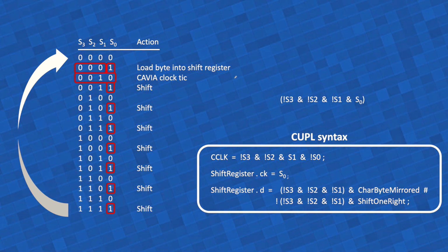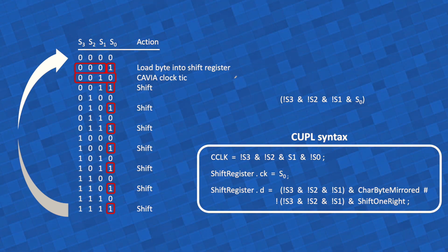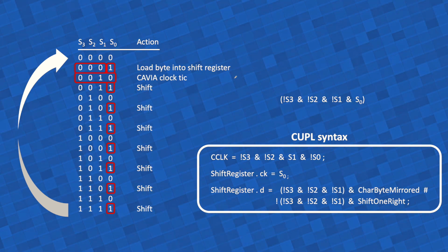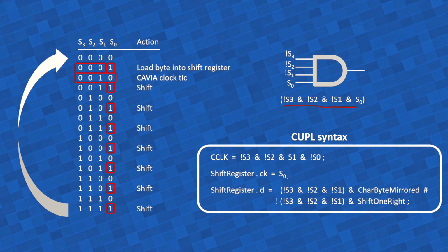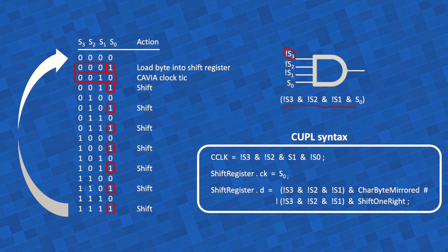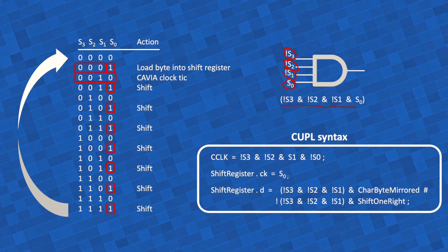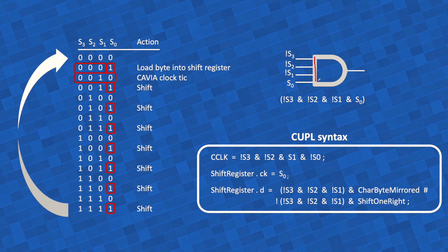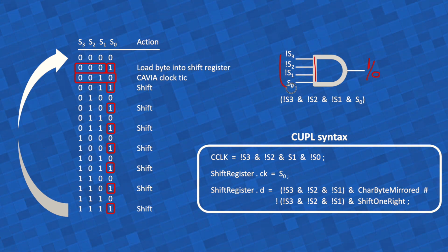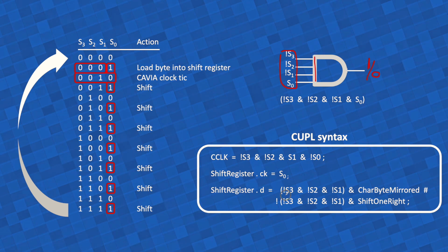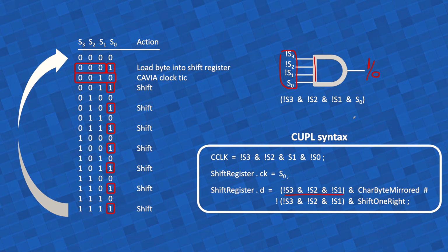But worse yet, if you did it, it would not work. And that's where you have to think about the physical implementation of it, not only at the level of logic abstraction. The physical implementation of something like this would be this. You would take 3 negated inputs and S0 not negated because you want it to be 1, and then you would AND them together, and this would be either 1 or 0 depending on the input values. And then you would say, well, I just put this whole thing here and it would work. Now, it wouldn't. Can you see why it wouldn't work?